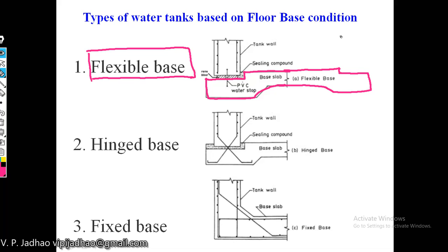Okay, so this is one of the walls and this is our other wall. Let us consider it like this. What we will be doing in case of water tanks with flexible base is providing some rubber pad below the wall like this. We will be providing some rubber pad like arrangement here below the wall.